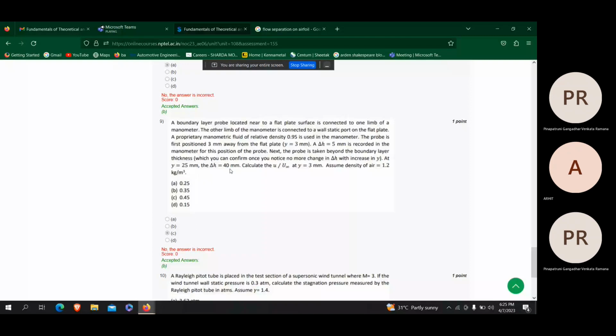That's correct. So now you have a stagnation pressure and static pressure difference in terms of manometric fluid. You can use the manometric relations and find the pressure differences and the respective velocity differences, right? Yes, sir. That we can find.